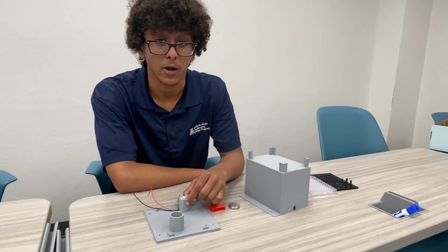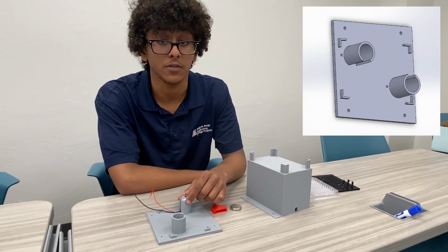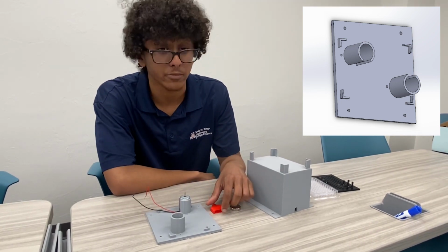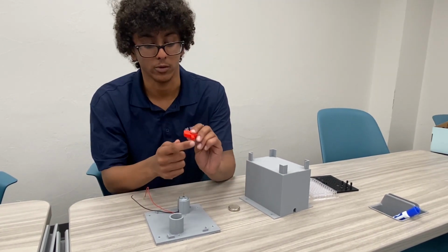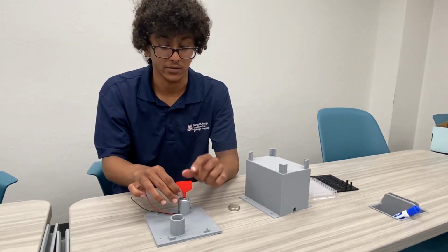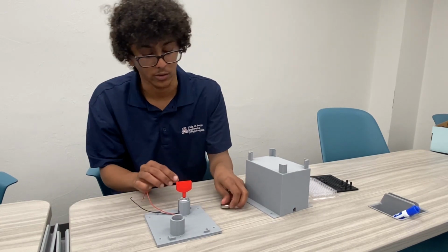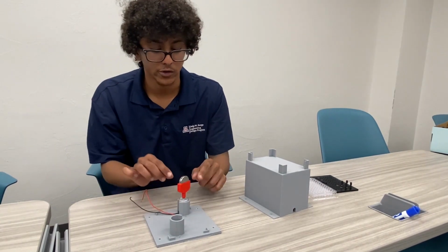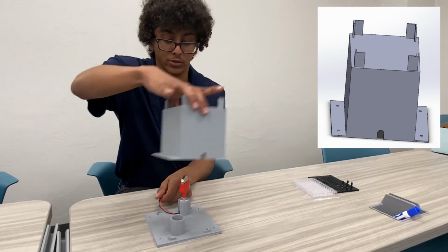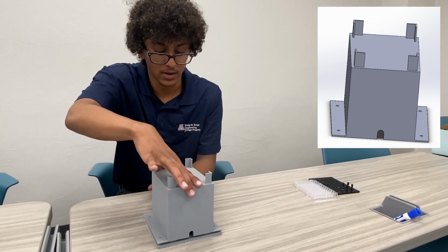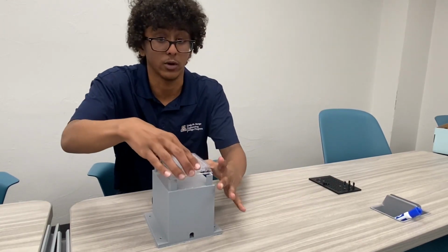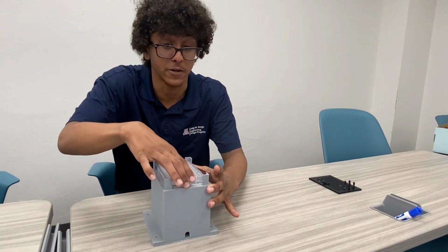Here's a magnetic stir housing fit with the bottom piece containing slots for the motors and wired connections to a breadboard. To attach the neodymium drive magnet to the motor, an external piece was designed with a hole cut out to fit the output shaft of the motor, and this attachment piece contains a tightly tolerant open space to house the drive magnet. Here's what the motor magnet assembly looks like. Naturally, there's also a top component to enclose the housing with ridges along the corners of the top that securely carry the 96-well plate during the device's use.